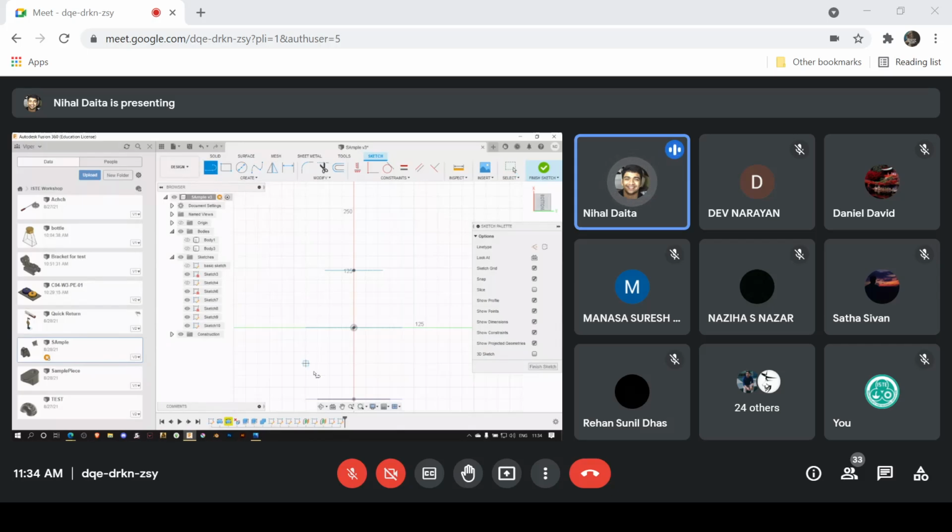Let's say I want to have a much sharper feature like this. I'm just drawing a line, so this will serve as a guide. Okay. If you're wondering how I'm drawing the curved line, basically you just click and hold, right, and it goes to that point. For some reason, okay. So here I need this end, right? Since that is not projected, I can just click on this element from another plane. I just click P for project and I click OK. And now I have that particular point with me, so I can easily snap onto it. Okay, I just did that.